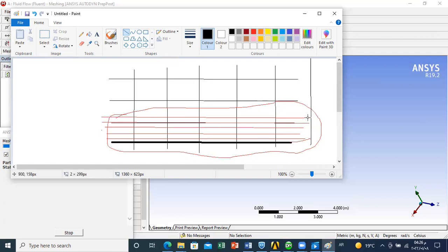You will have a sudden cut in the inflation, which will lead to divergent zones. While if you do inflation for all of your surfaces, the inflation will be continuous. What I mean is that here, for example, the inflation will be like this. So you will not have a cut in your inflation. It will be like this.